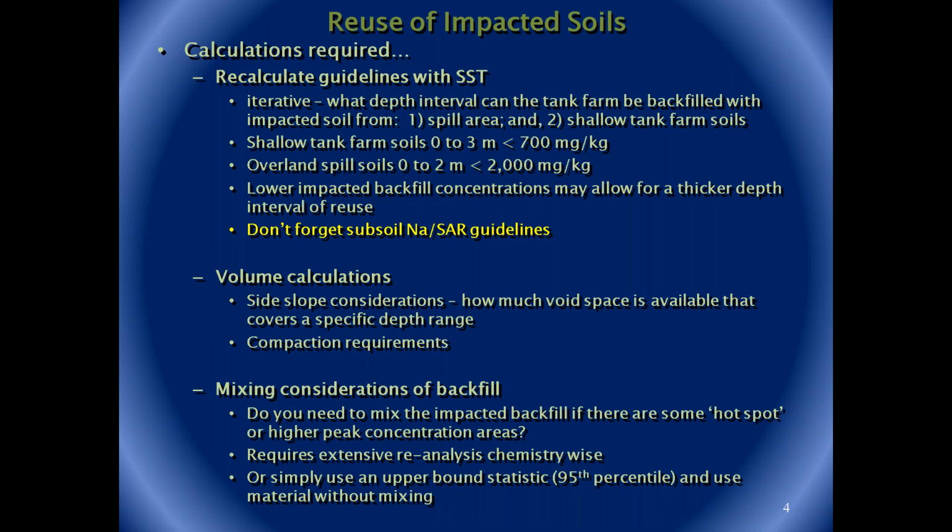The other one is volume calculations, and also considering things like side slope, where you have a larger area at the surface and a smaller area at the bottom. We don't always see that on our excavation diagrams. You don't always see people putting in the slope, but it's important because it affects your volume. And of course, you're going to have to consider compaction requirements.